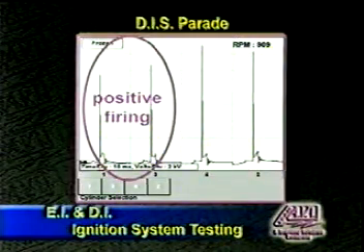Well, number 1 and number 3, we can tell you right off the bat, is a positive firing event. So looking at my other hand, when this spark plug fires backwards, my KV probe is here and current flows this way. That means that our KV probe is picking up the voltage potential of the firing event after the voltage drop across the spark plug air gap. It really makes no difference. The only reason why we tell you this is you're not going to have that 20% uniformity on KV values when comparing cylinder to cylinder.